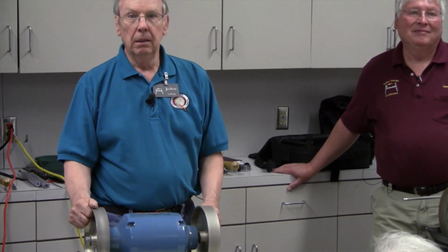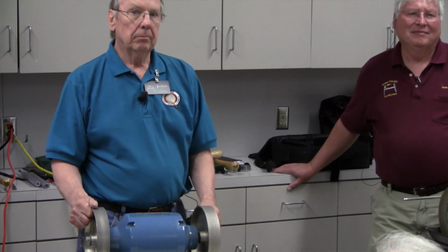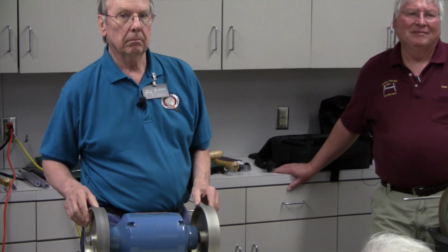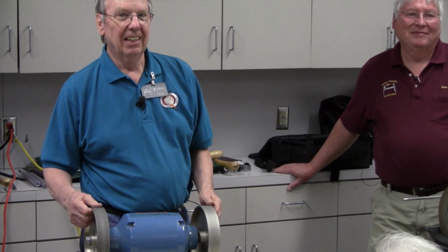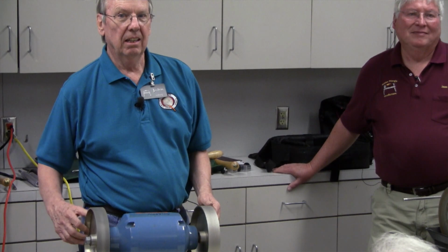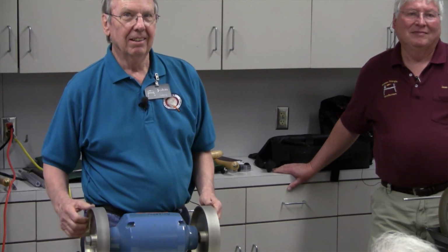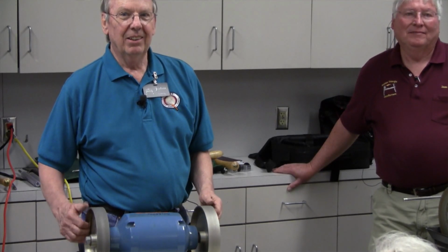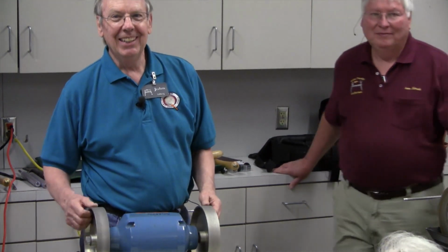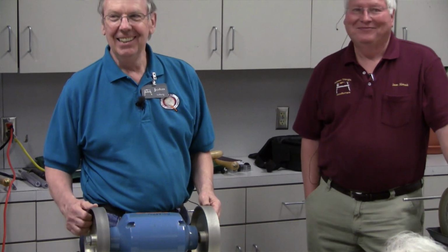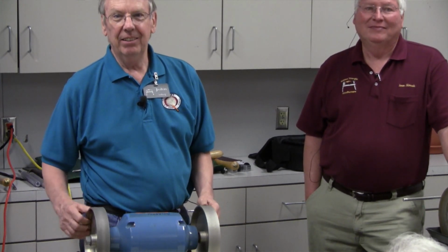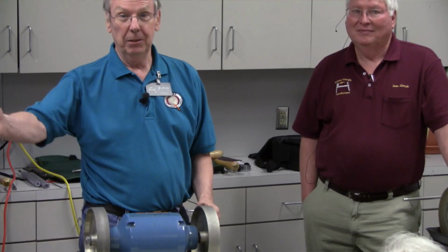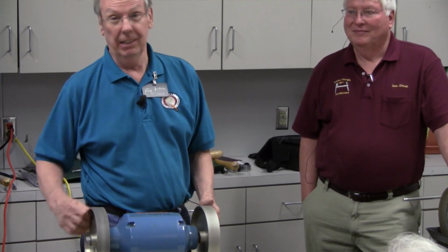John? Is there anything in the literature that, I keep wondering, for example, turning dry pecan, which I'm sworn off, that you would change the angle and have less of a pointed edge? Yes, there is. You'd stay at 45-ish versus. The question John's coming up with is, dry pecan is like concrete, do you want a different angle for a really hard wood than you do for a soft wood? And my friend John Horn says yes, there is. I have not seen anything like that. So.